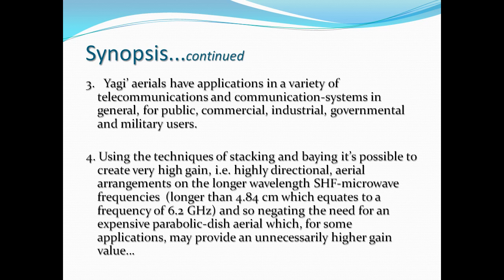Number 4. Using the techniques of stacking and baying, it's possible to create very high gain, that is to say highly directional aerial arrangements on the longer wavelength SHF microwave frequencies, and so negating the need for an expensive parabolic dish aerial which, for some applications, may provide an unnecessarily higher gain value.